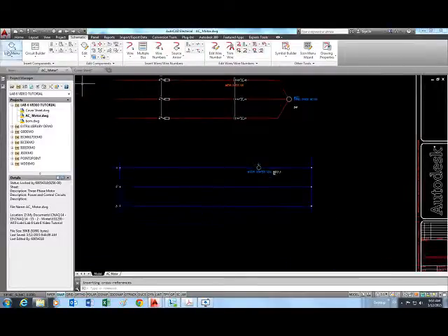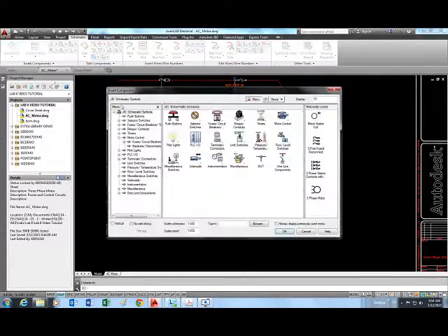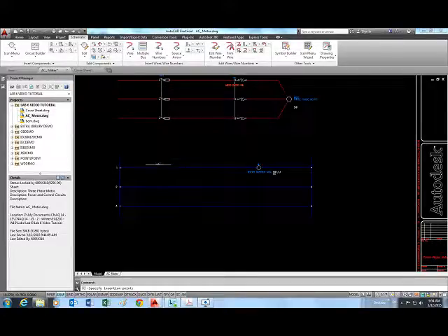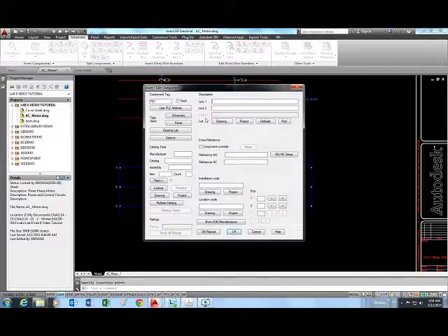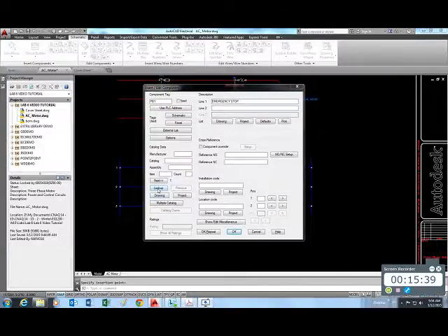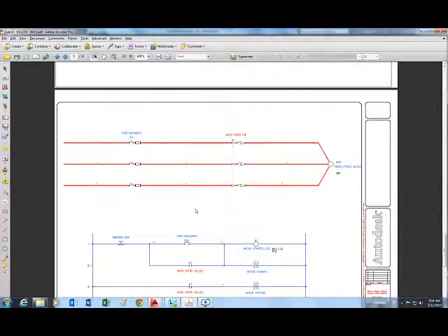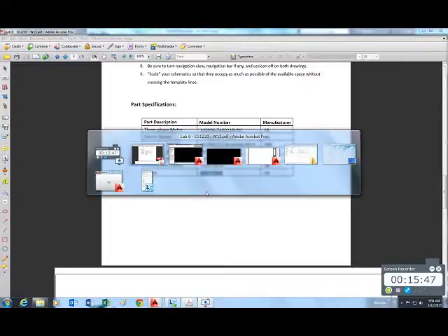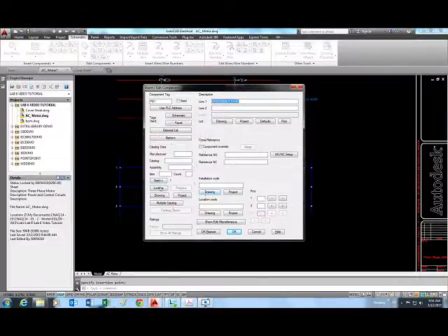Okay, let's put now the emergency stop, push button, and the momentary contact. So here's the normally closed mushroom type push button, and this is emergency stop. Right, now the model number is again in this table made by AB. Okay, look up.